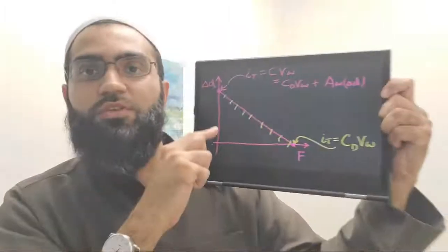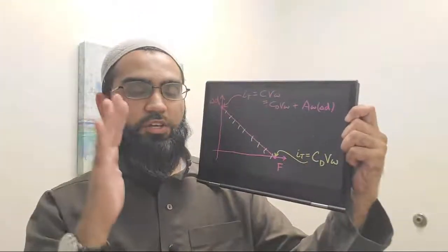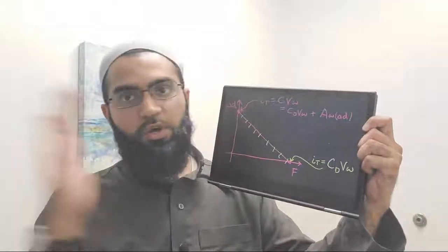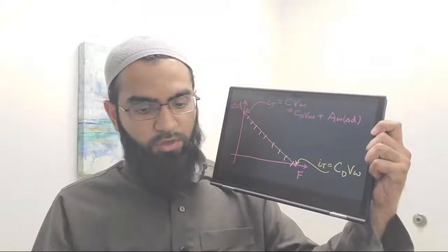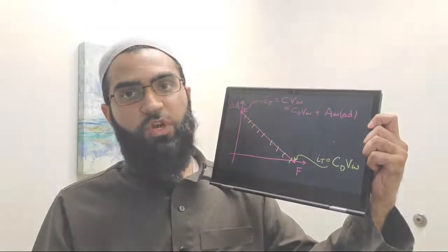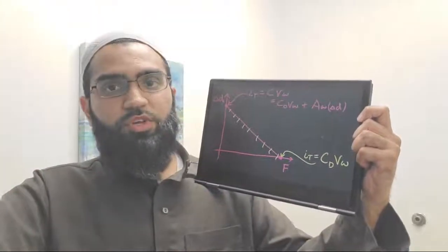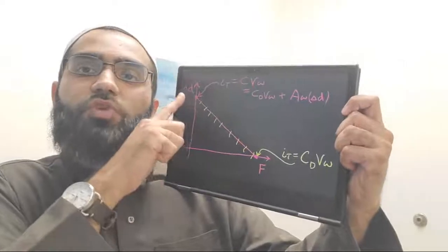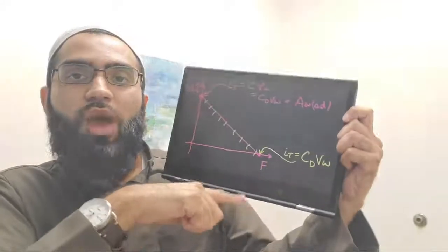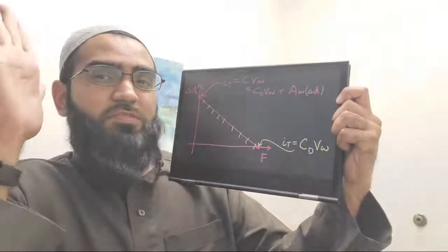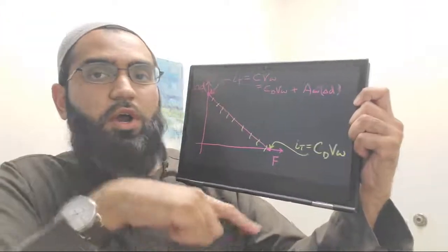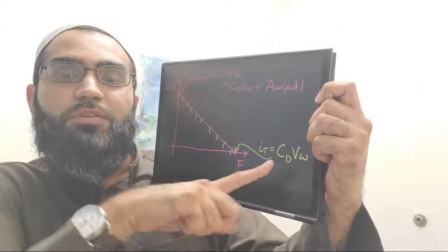Now, what happens here is as you travel down this line, if you have, let's say, an external force, whether that be a spring or mass loading, pushing back on your actuator from force equals mass times acceleration. As that mass is getting pushed back and forth, it's causing resistance, or force, to be opposite. That's going to make you travel all the way down this line until, if you have an infinite mass or an infinitely stiff spring in parallel with your device, you will only have your clamped capacitance. That's actually something you can't really measure directly, because you're not going to get into a situation where you are truly clamping your device.